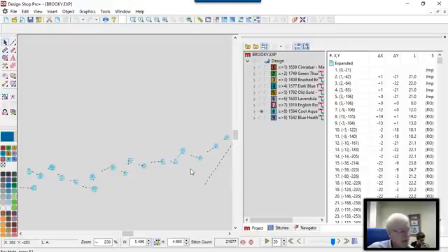Oh, exactly. So yeah, there's a lot of times the machine is always going to benefit by keeping running instead of stopping, like I've said before, for every 1/4-inch letter and stuff like that, or every dot. You got to get a rhythm going. Another tip I've mentioned before, I'll go over again, is if I was going to trim each one of these dots, when I digitized it, I'm going to jump from one end to the other, making sure that the hoop is moving between trims. The reason for that is you want to clear the tail of the thread trim out of the hole in the needle plate before you start stitching again, or it can get tied in together and you get other problems. So that's a side note.